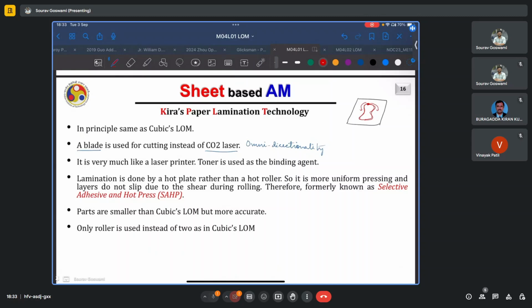However, typically you would use a blade which has only one cutting edge. Say this is a cutting blade that we are using attached to some holder. Say this is the cutting edge. Now we are constrained to always travel along this direction. Even if we have two cutting edges, we can only move along the plane. We cannot say we want to move out of this paper or into this paper. That is not possible because that is a flat face that cannot cut the contour. Thus, the omnidirectionality of the process gets affected, and we must take extra care in the process planning step to come up with suitable tool paths.